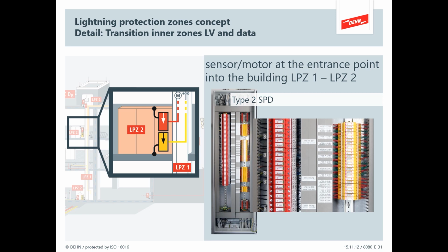Because the surges are not going to just go down the power lines, they're going to go down any conductive cable. So that's your controls, your comms, anything like that. And all of those cables, you have to think, if that cable takes down a piece of equipment, which means my air handling unit stops, and that's catastrophic for my data center, then it's going to need some form of protection.